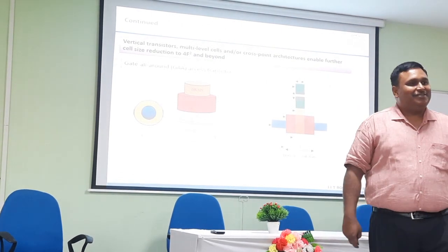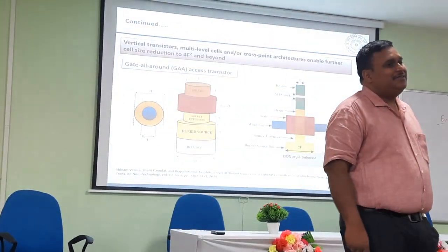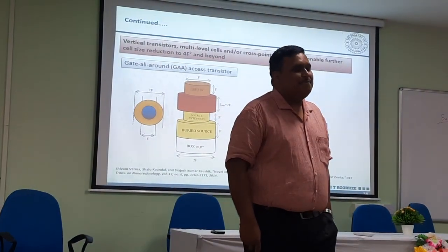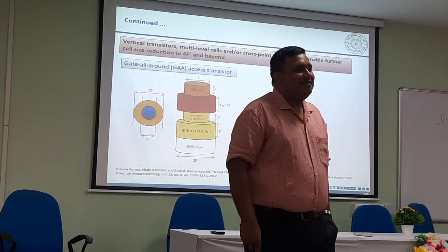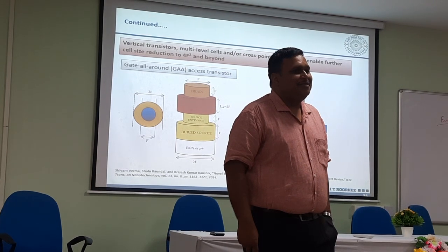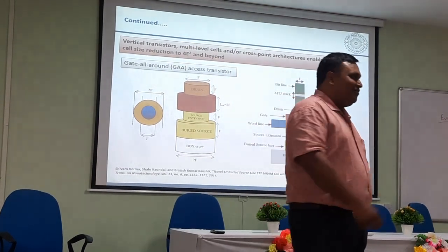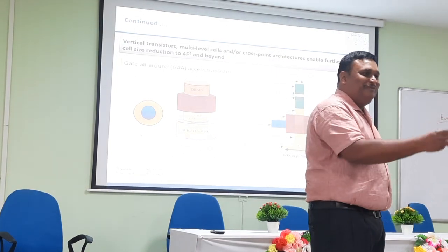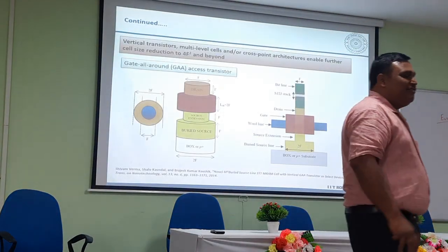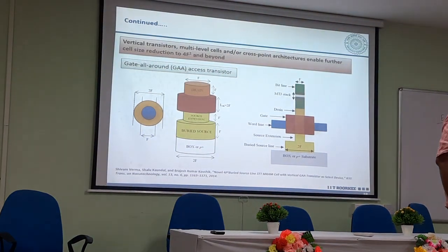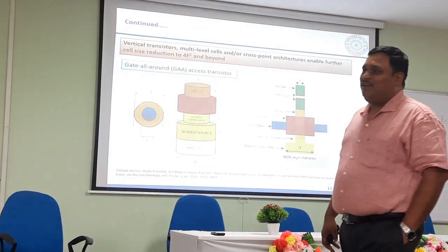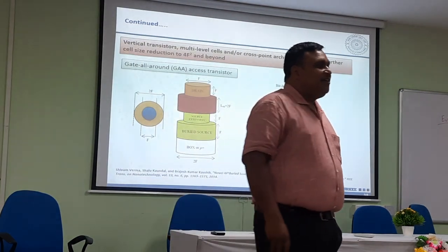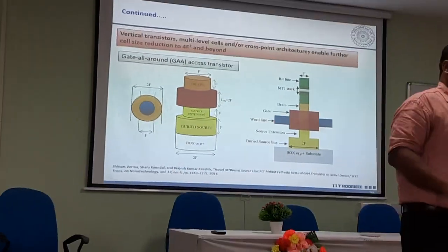Yeah, please go. I will ask a general question. We have seen a lot of MRAM, and yesterday we got a lot of motivation about PCRAM. What about RRAM? Does it have any prospects in the future? Yeah, of course. Professor Jawar Singh, there are many; Shritosh would also have spoken about molecular RRAM. But oxide-based filamentary RRAM took off but did not go to the industry. The pertinent reason, in a nutshell, is reliability.